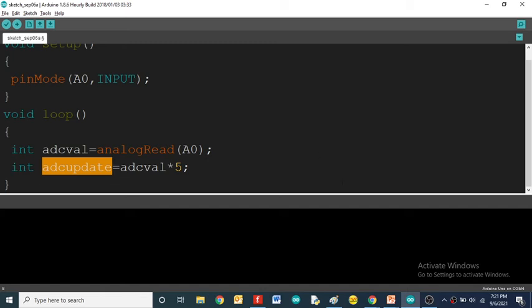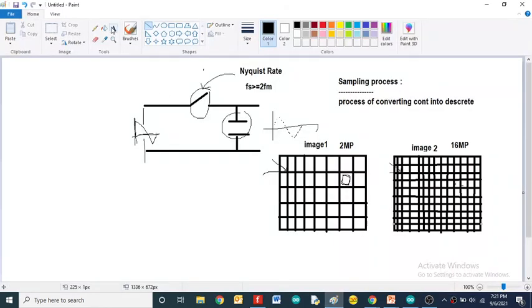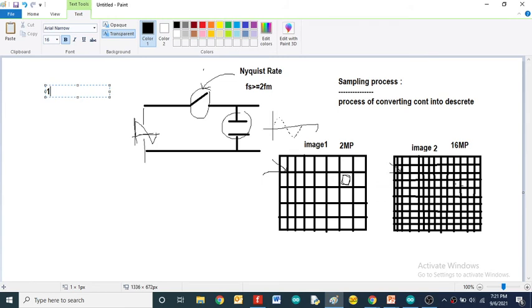Okay. So let's say the room temperature is 1 degree Celsius, then it will give 10 millivolt, or the value 10. If the degree Celsius is 2, then it will give 20. If the degree Celsius is 10, then it will give 100.